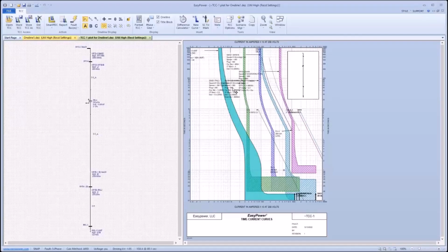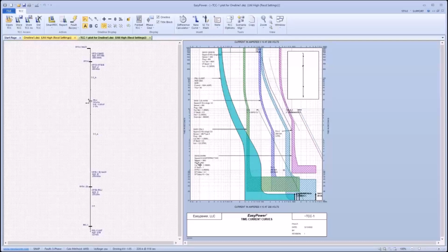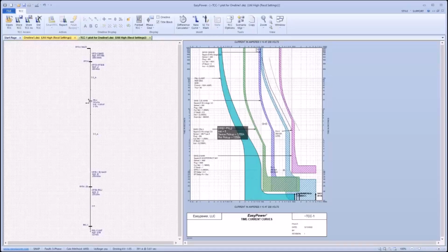And now before I organize all this, I won't do too much of that for sake of time, I'll delete a few things here just to clean it up. Let's just say we'd like to take this breaker here, the feeder to panel 3. Obviously, we would like that to coordinate with the downstream panel, the breaker in panel 3. So let's just make that settings change. I believe these are LI breakers, so not too much we need to worry about here. Make sure that we're clearing inrush with the upstream feeder, which I believe we are, yes. That's good enough for our purposes here.